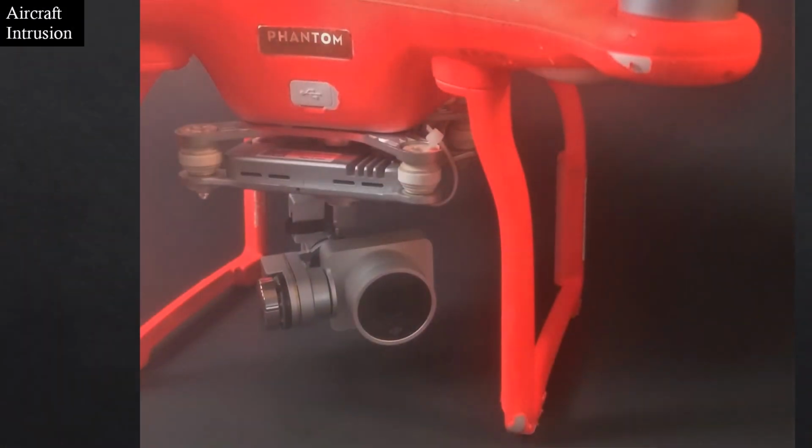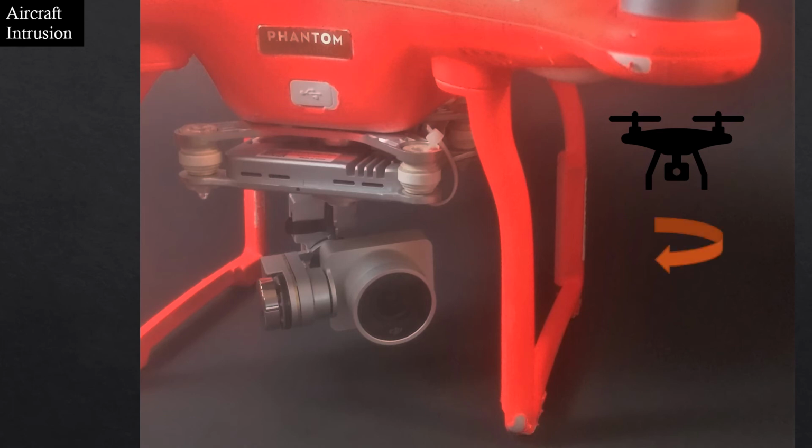Aerodynamic forces may be another reason why aircraft intrusion is happening to you. In our scenario here, the drone is flying towards you and the camera is pointed at you. Then we've maneuvered with clockwise yaw and are heading in a new direction. So the drone is moving down this new heading, but due to mechanical limitations of the gimbal and the influence of aerodynamic forces, the gimbal has a recovery delay before it points in the right direction. You can see how the landing gear can easily intrude during these recovery periods.